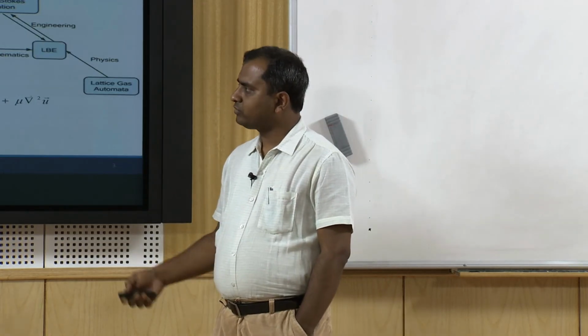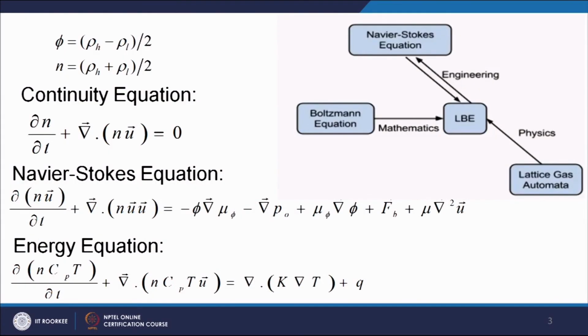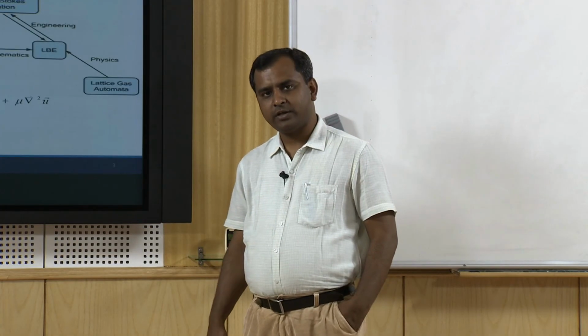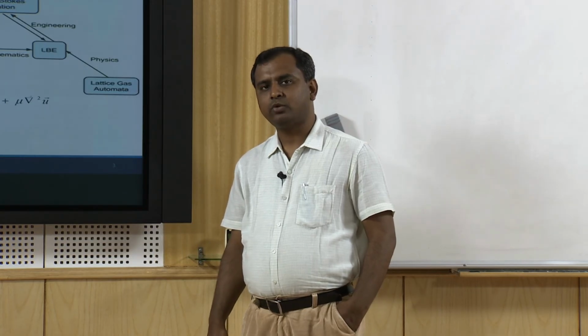Similarly, one can write down the Navier-Stokes equation. You know that we will have two Navier-Stokes equations, that means momentum equations, for gas and liquid. Once we add those two equations, we will once again get an equation having n as parameter. On the left hand side we have the unsteady and inertia term, and on the right hand side we have the pressure gradient term, viscous term and buoyancy term. Apart from that, we are introducing two new terms. These come from the chemical potential, from chemical thermodynamics. If you write down the species-based momentum equation, then these chemical potential terms come into the picture.